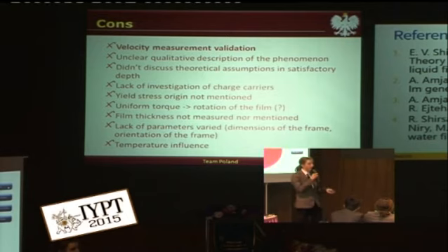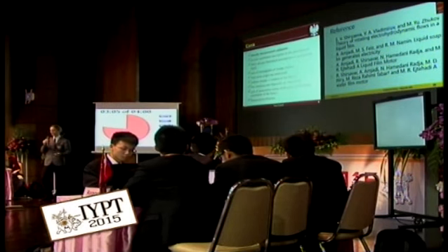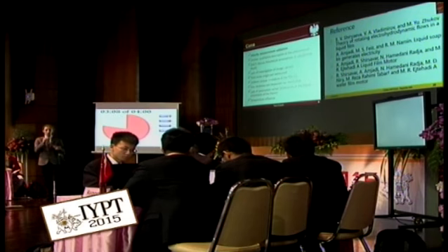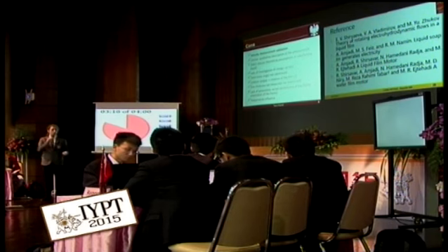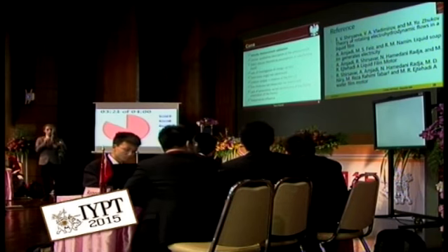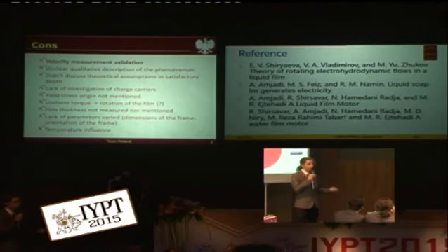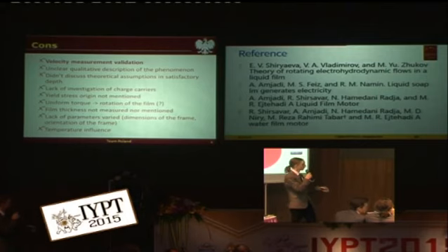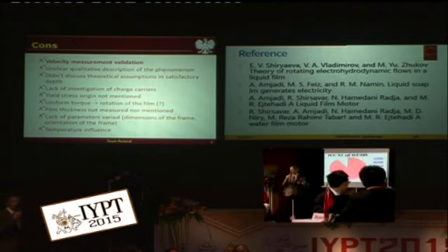You didn't say anything about the film thickness. I don't know at this point from your presentation, is it a millimeter width or nanometer width? We didn't have even an order of magnitude. You also didn't say what is the origin of the yield stress. It's a weird phenomenon for fluids to have one, so I think it should be properly introduced in the presentation. Also, you said that the conductivity is finite, so the Joule heat should be included in your presentation, as it would heat up the whole fluid and limit its time of operation.